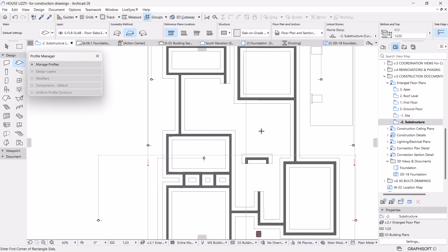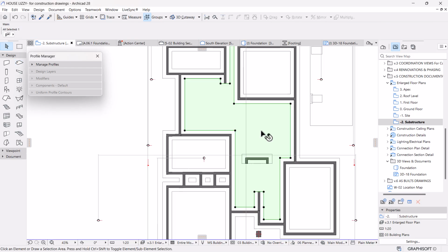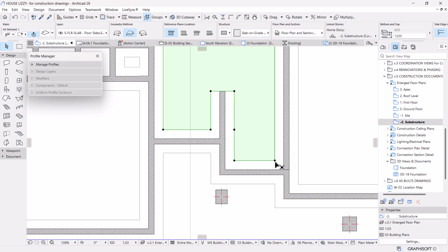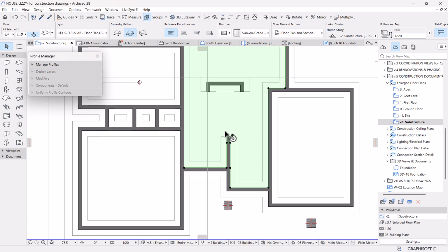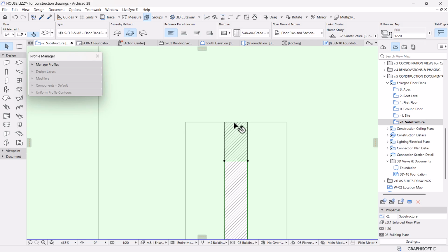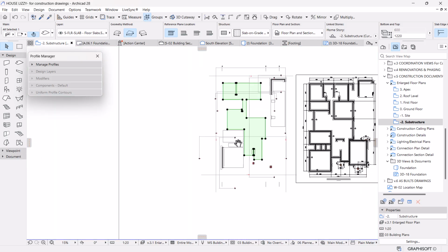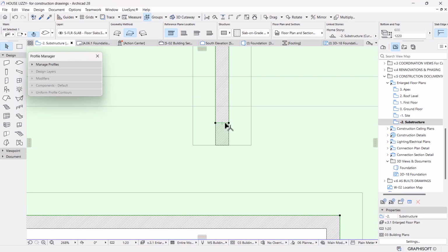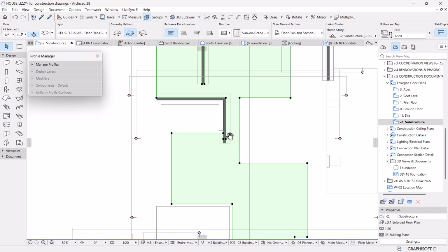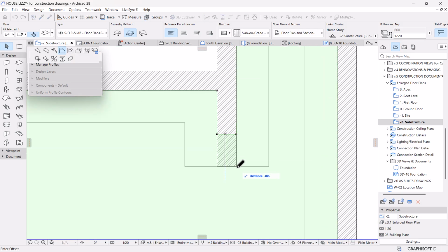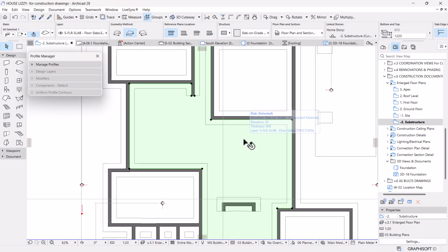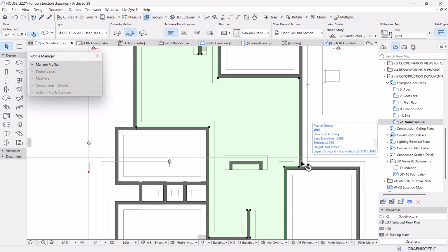You can magic wand and try to apply the slab once like that. Let's select the slab. Then I'm going to offset all edges right all the way to the wall side, but there will be areas like this that need to be fixed. I think one of the areas is this one. We've got another one here. Then we should be good to go.